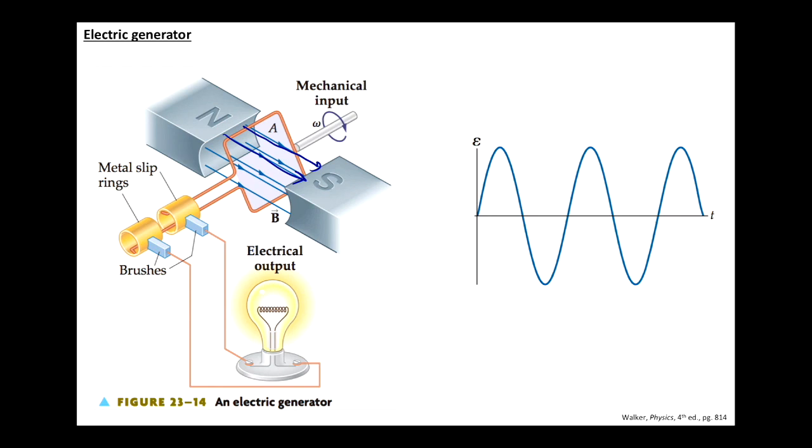The thing is, the rate of change of magnetic flux changes as it rotates, because of how the area is effectively decreasing, which means we're going to get a change in how much current we get. But also, keep in mind that once it rotates halfway, now we've sort of flipped which side the magnetic field is going into, which means that now as the flux changes, it's changing in the opposite direction. So not only do we have a varying amount of potential that's created, we have a potential that's flipping direction as well.